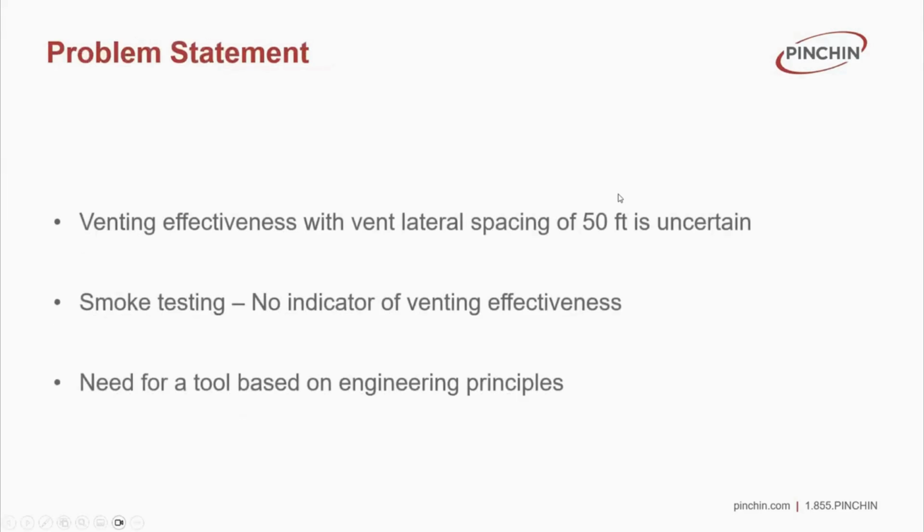So the problem statement for this is that venting effectiveness with vent lateral spacing of 50 feet is uncertain, because we do not know, if we space out at 50 feet, whether the entire space between the two vent laterals is going to be actually vented out or not. Sometimes we do post installation smoke testing to see the venting, but it's really no indicator of venting effectiveness.